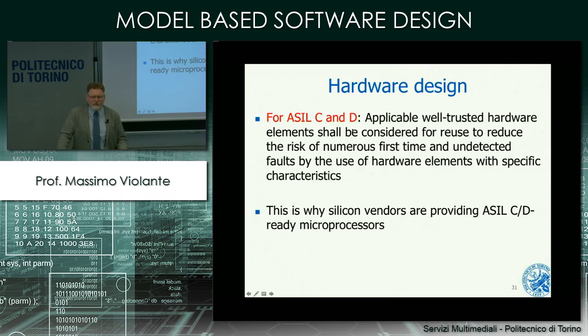The manufacturer of that specific microprocessor that is ASIL D compliant put at work a number of techniques that guarantee you that no matter what is happening inside the microprocessor, you will always know whether the microprocessor is working correctly or not. So you don't have to take care of understanding whether the microprocessor is faulty. This is done automatically for you.